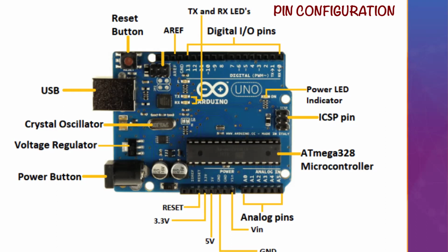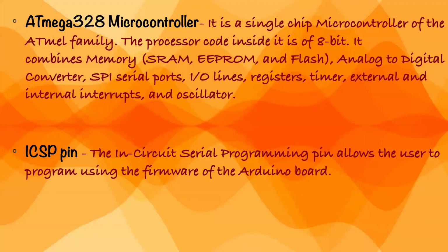Okay. If you just want to blink it in some simple manner, we don't even need that external LED. Why? Because if you give 5 volts to this 13th pin, that is digital 13, D13 pin, it automatically refers to this LED. So this LED can also be used for that type of programming, projects, or verifications, right? You don't need an external LED for it.